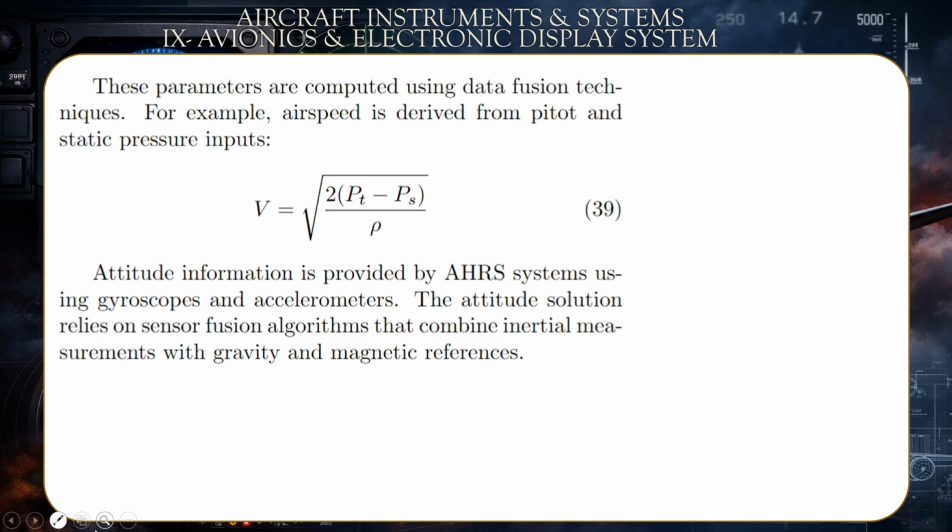Now, as a reminder on how we get the value of the velocity, so you have total pressure is equal to static pressure, which is PS, plus dynamic pressure, which is Q. Now, dynamic pressure is equal to what? Q is equal to 1/2 rho V square, with rho the density of the air, ambient air, and V the velocity of the flow, okay, of the airflow.